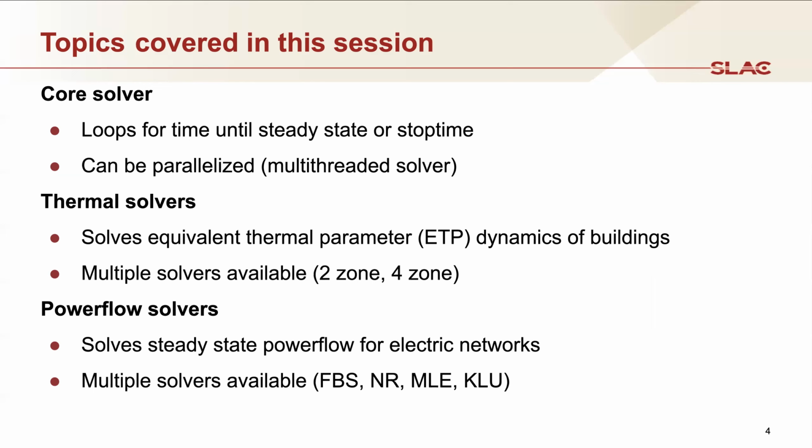And then once it solves the steady state of every object, it uses the object's time step to figure out what the time step for the whole simulation is, and advances the clock, and then redoes the process over and over until every object states that it is essentially running in steady state and no longer needs to advance the clock. The core solver can be run parallelized, so we can actually solve multiple individual solvers simultaneously where that's possible.